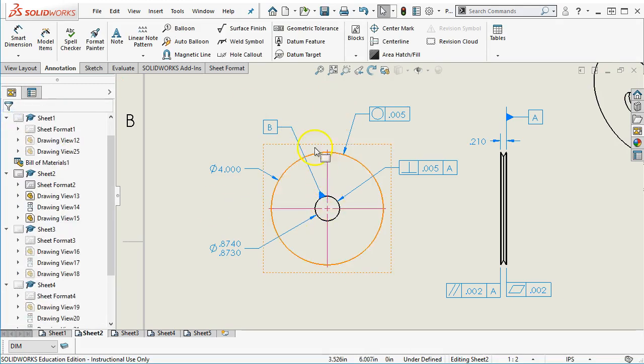when I go with B, I'm not sure about the correctness. You know, we established the perpendicularity. I assigned that to B because that's still the critical. Then in that case, really the circularity or cylindricity would be applied to this face, and then the outside would be the concentricity.